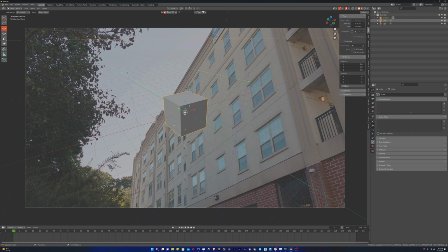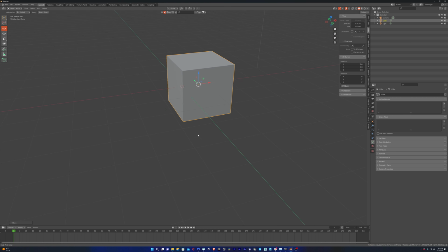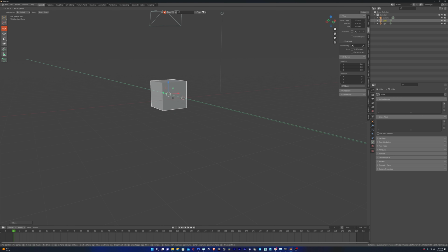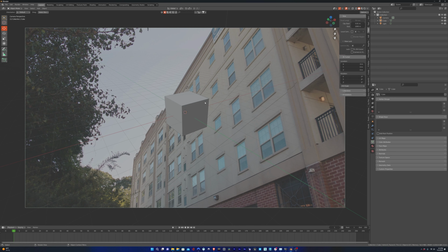If you select something, you hold shift and you hit spacebar, you can select move, rotate, scale, transform, and a bunch of other things. So I just selected move, and now we have this gizmo here. The x-axis is left and right. If we're out like this, x-axis is left and right, y-axis is the depth, and z-axis is up and down. I'll press 0 on the number pad to go back into the camera view. You can kind of see how this lays out.